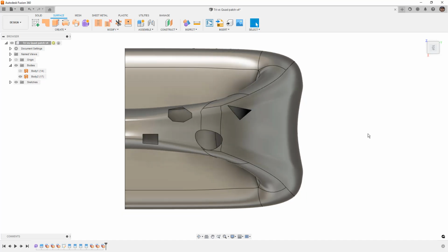Now I want to take a look at both patch and loft in all of these cases, which might seem counterintuitive. And I want to highlight the sort of pluses and minuses or pros and cons of each in each case. Because there will be problems with both methods in all cases. Now, you're just going to have to deal with that. It's just the way that surfacing tools are working in Fusion 360 and honestly in a lot of CAD softwares. They're just not meant to do complex surfaces. So we're getting a little outside of the realm of what some of these tools are designed to do.